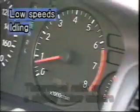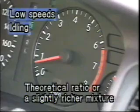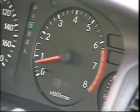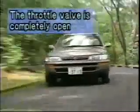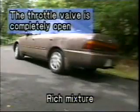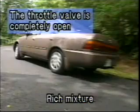When the engine is idling, or when the vehicle is traveling at low speeds, fuel and air do not mix well. Because of this, it is necessary to achieve the theoretical ratio, or a slightly richer mixture. A greater ratio of fuel to air is necessary to obtain the needed power when climbing hills or other times when the throttle valve is wide.